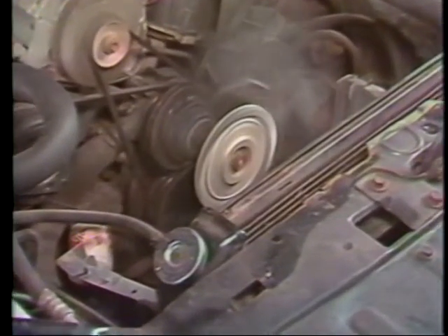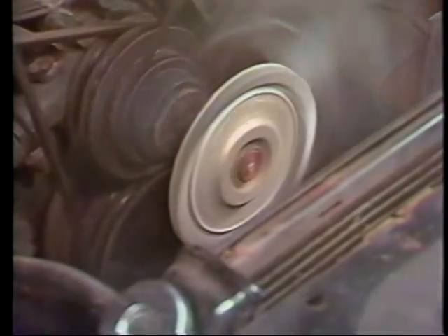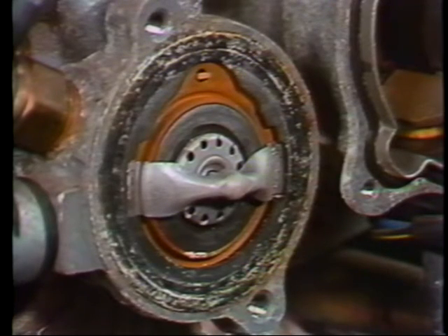As the thermostatic spring heats up from hot air passing through the radiator, the clutch reduces the fan's slippage to increase airflow through the radiator. A defective coolant fan clutch could allow the fan to slip when the engine is hot, allowing the engine to overheat when the vehicle's not moving. Technician A's statement is true. Looking at Technician B's statement, if the thermostat was stuck closed, the engine would overheat all the time. Technician B's statement is therefore false. The correct answer is response A for Technician A only.